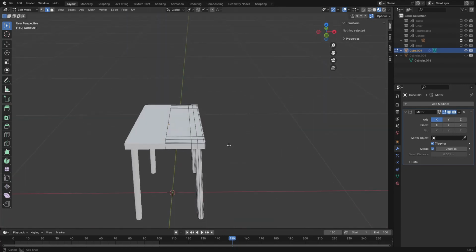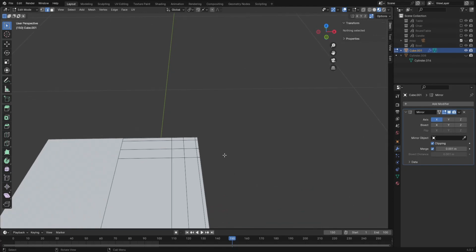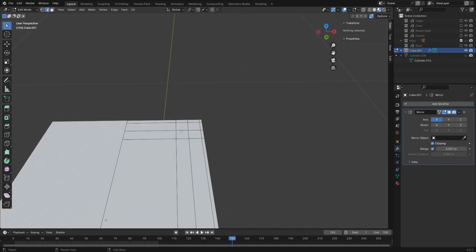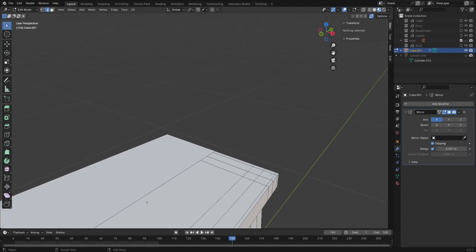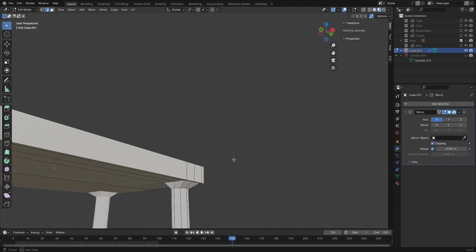The last thing we miss is the backrest that we create now. Here we already have some geometry that we could use, but for the sake of speed we will do it the fast way. You can later remove all the unused geometry by dissolving the edges, how you learned it earlier in this video. If you instead want to connect the meshes, you can do it like we did it for the bottom side of the seat here.